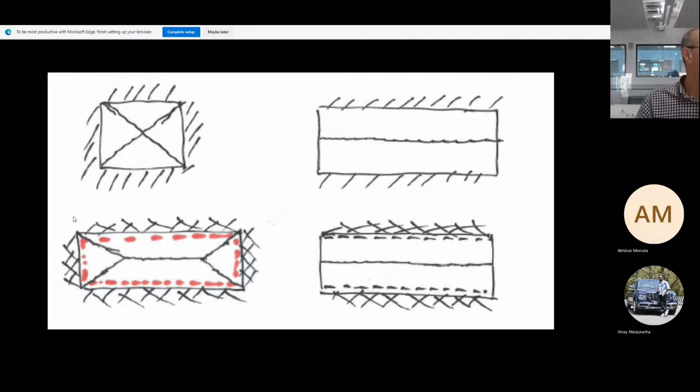You have a negative moment, a hogging moment, isn't it? Like a cantilever: at the end you have a negative moment at the support. It's exactly the same here. We have positive moments in the middle, but negative moments at the fixed support, and therefore we have negative yield lines in addition to the positive yield lines.